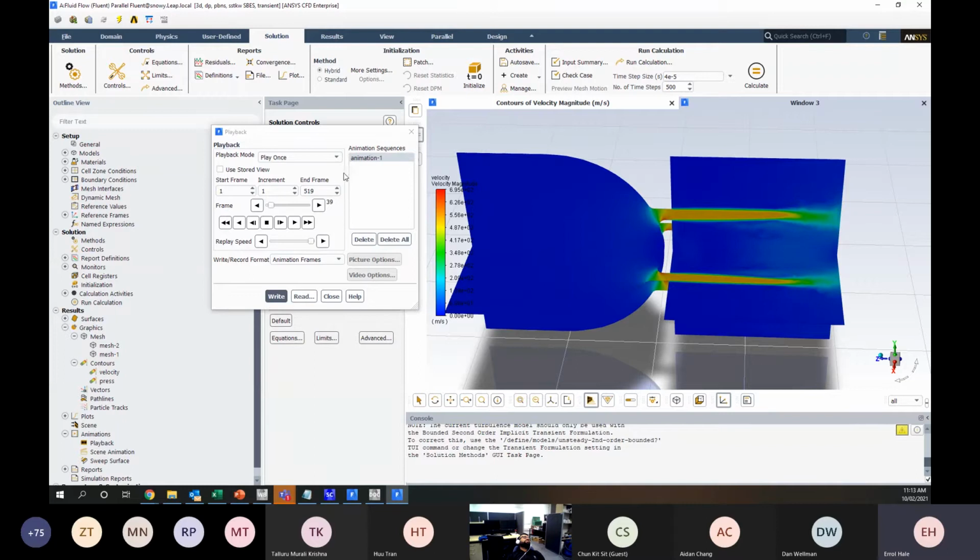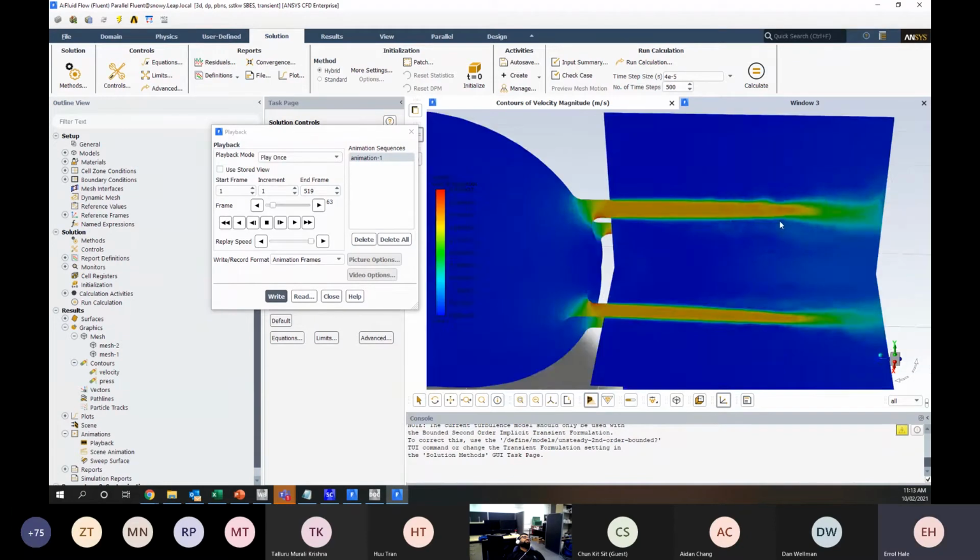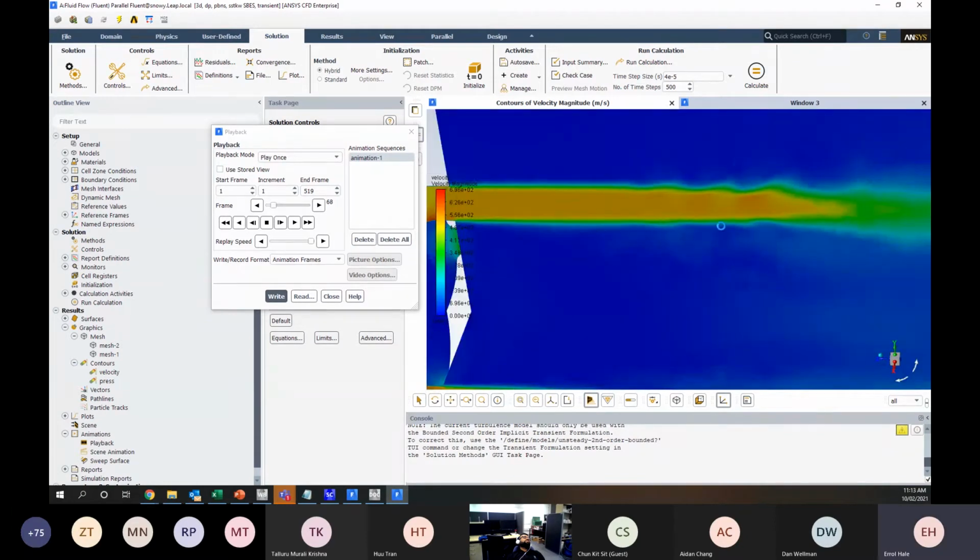We've got 500 frames to get through. Just seeing here now the flow start to break up a little bit and become turbulent. So there's been a transition. The flow has become turbulent, and we're picking up those turbulent structures in our SBES model.